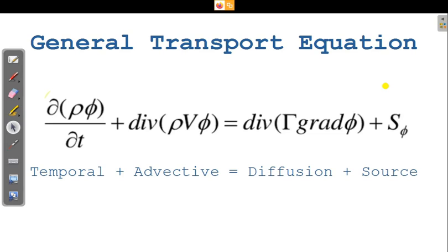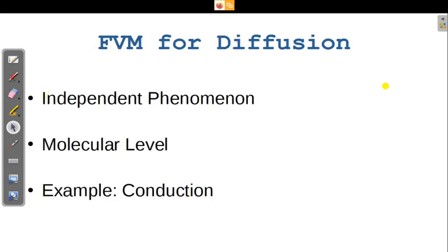On the right side corner, you have this S phi. This is a source term wherein you can have a gravitational term, or dou p by dou x, which is a pressure gradient term, or an electromagnetic or magnetohydrodynamic term, or whatever term you want. So I will give more importance to this equation. Please understand this equation and try to derive your governing equations from it. This is what the book essentially deals with. Each and every term in this equation is a chapter of that book.